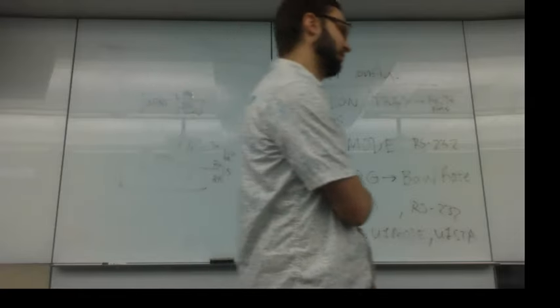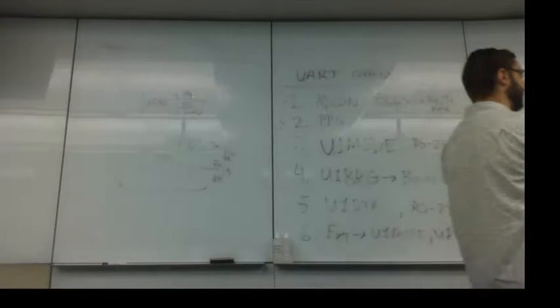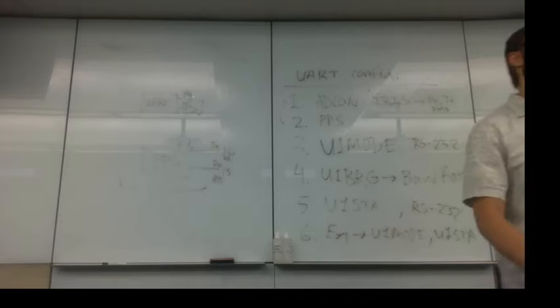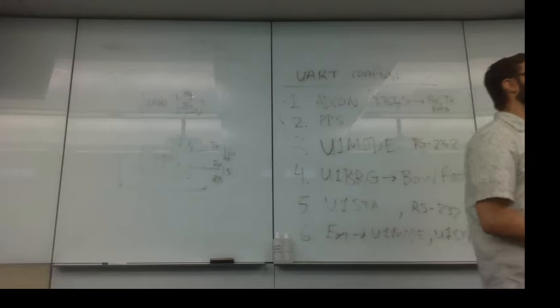That's one of the things about RS-232: it's been around so long that there's no real common implementation, so as long as the client and server are in agreement about the implementation, then it's okay. But in general, it's not a very strict implementation. USB, on the other hand, is extremely strict, and so that has to be the same across a wide variety of devices.